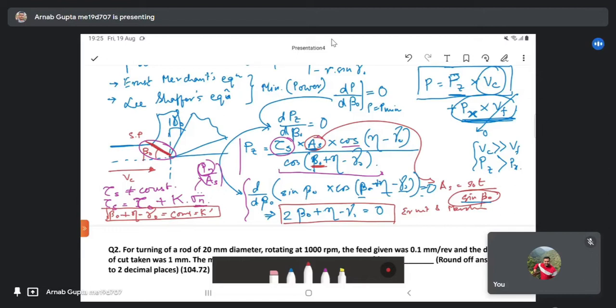So by applying the slip line theory and by drawing the Mohr circle at this particular region for the planes, such as this primary shear plane, there's another secondary shear plane over here, and the plane along which the stress is 0, that is where the chip is getting detached from the tool surface. There both shear stress and normal stress value will be 0.